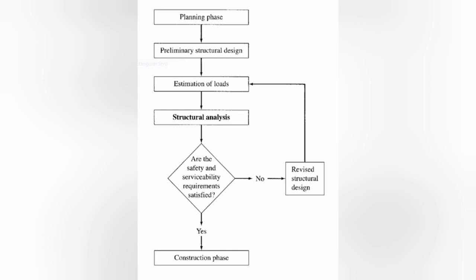But if your structural analysis by safety and serviceability check does not satisfy, it's not enough for safety. It does not reach the minimum requirements based on the codes. You will go back to the estimation of loads. So you revise the structural design.